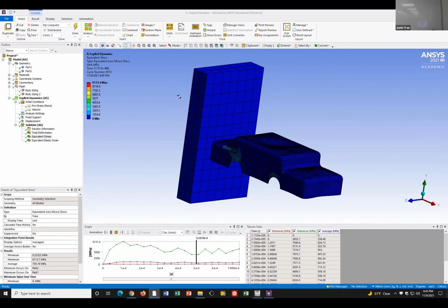You could assume that they're closed. When I say it's not linear contact, frictional or nonlinear contact actually allows a separation. As long as we don't have any separation, we can say that we bond the contact. So for these ones, I wouldn't expect there to be any separation.